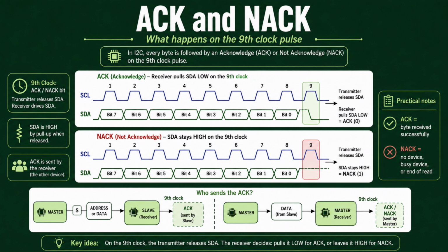For a NACK, the receiver leaves SDA released, so the pull-up resistor keeps the line high. A NACK after the address may mean that no device uses that address, the peripheral is not powered, the wiring is incorrect, or the device is temporarily busy.